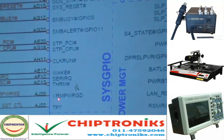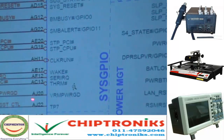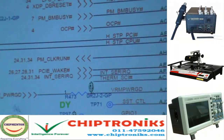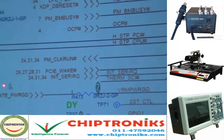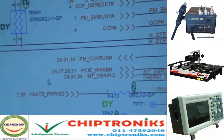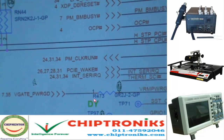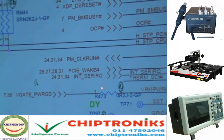Then you have VRM power good. This is very important. VRM power good is coming from the CPU voltage, the CPU regulator. You can measure the voltage across this resistor.